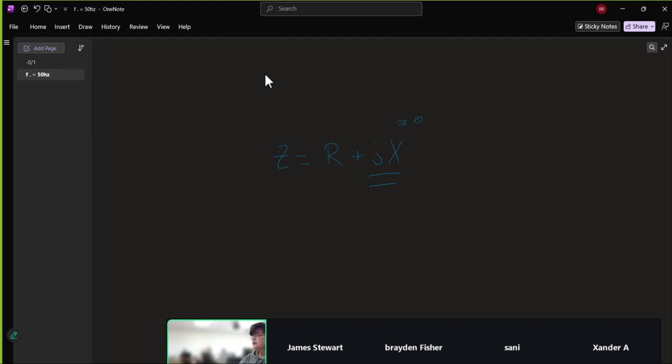So let's say your original circuit impedance is 8 minus j2. You proved in Circuits 1, or it's in the Circuits 1 book, that you get maximum power transfer when the resistance of your load is equal to the R Thevenin of your source. So the resistance would need to be 8, but we want our imaginary part to add up to zero.